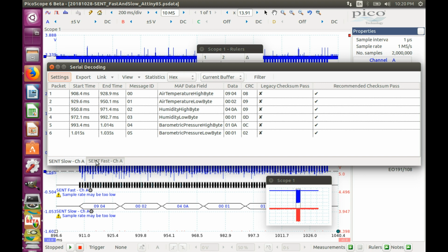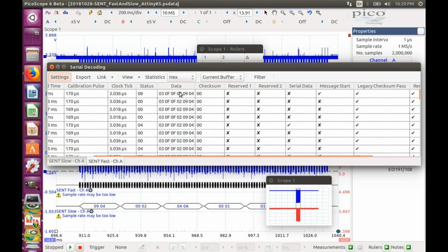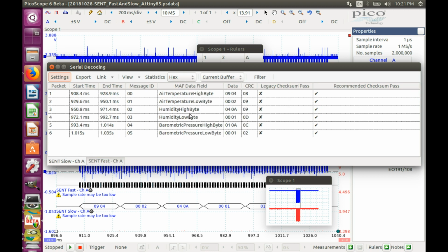Yes, it does. We've seen this number already in the fast channel right here, 294. This was for ADC channel 2, and this is no surprise because both channels 2 and 3 were connected to the same potentiometer, so they should give similar, or in this case exactly the same values. So we do have the correct data transmitted.